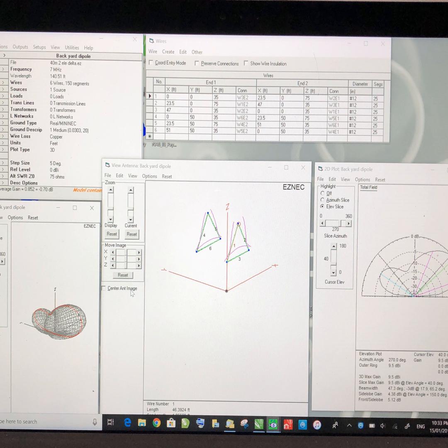So normally, once you've designed the antenna, it's time to build it. And this is reasonably straightforward. The modeling software gives you the length of the wires and indicates obviously where the feed point will be. So it's just a question of choosing the wire you'd like to use. If you want to keep it inconspicuous, you can use a fairly thin wire. You don't have to use a thick wire. On the HF bands, it's not really going to make much difference with the thickness of the wire.